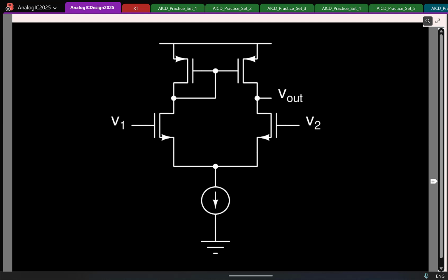So here the main point to have in mind is, although this is asymmetric, when can you claim the circuit to be symmetric? We have common mode excitation, which means the gate to source voltage is same for both of these transistors, NMOS and PMOS, right? So as long as I have the same VGS, which means I have common mode excitation, what can you say about the two drain voltages?